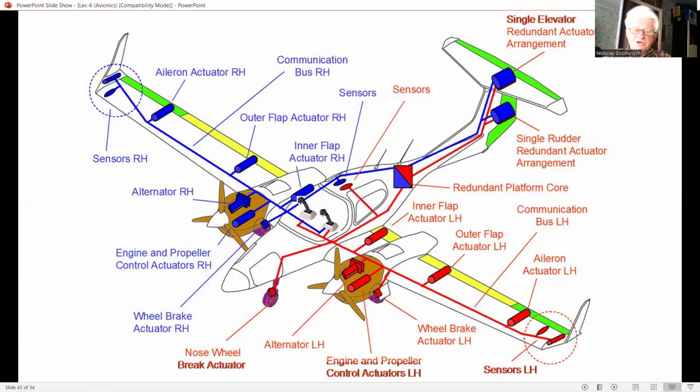Fourth, oscillatory failures, whereby the sensor output is oscillating, the amplitude and frequency being dependent on the type of failure. Loss of feedback, for instance, can result in a stop-to-stop oscillation. Fifth, soft failures, whereby the sensor is functioning, but its output is outside the specification tolerances. And sixth, intermittent failures, whereby the sensor fails and then recovers intermittently.